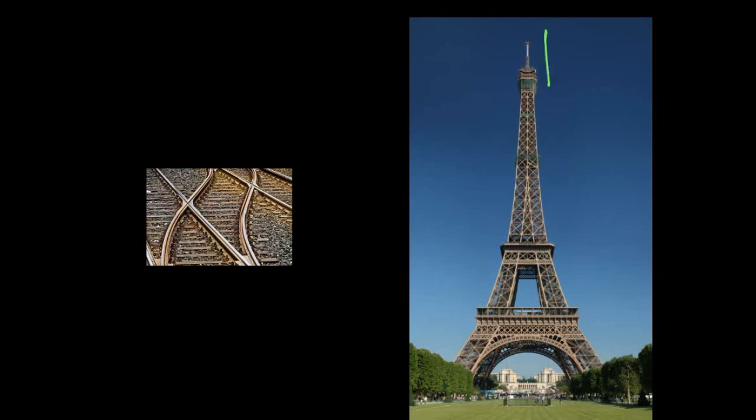The engineers, in one of the towering achievements of the human mind, allow the Eiffel Tower to expand and contract freely. Is that a good idea, or is it not a good idea? I would say that's a wonderful, brilliant idea to allow the Eiffel Tower to expand freely and contract freely, because if they arrested the expansion, that would lead to the manifestation of thermal stress in the steel structure.